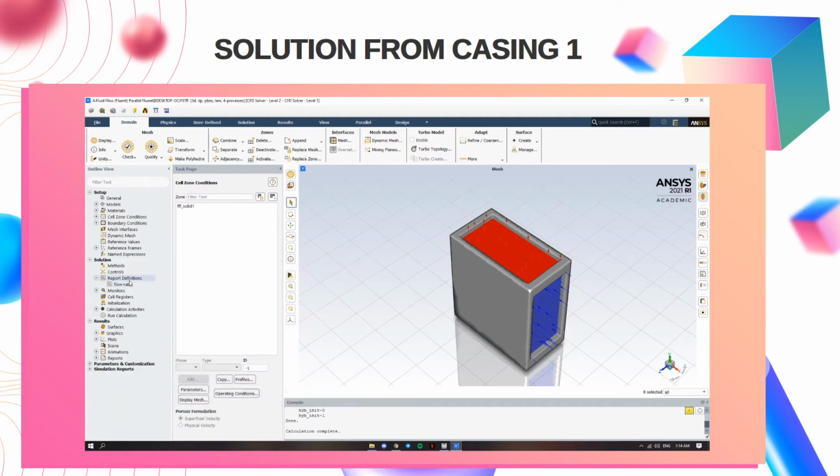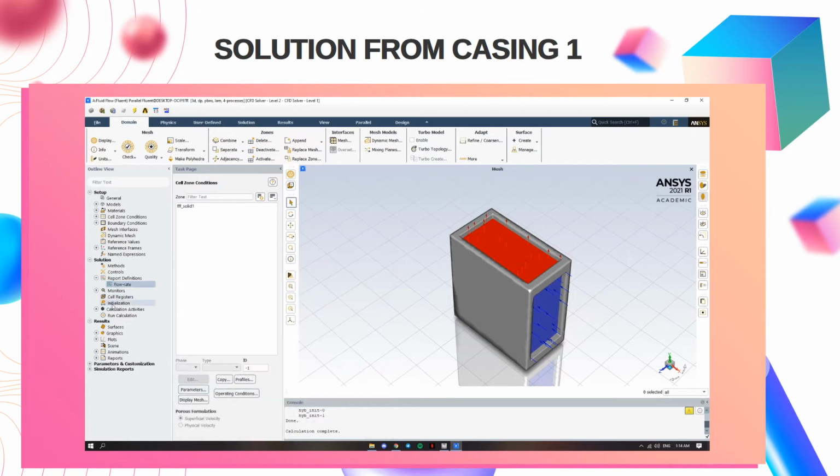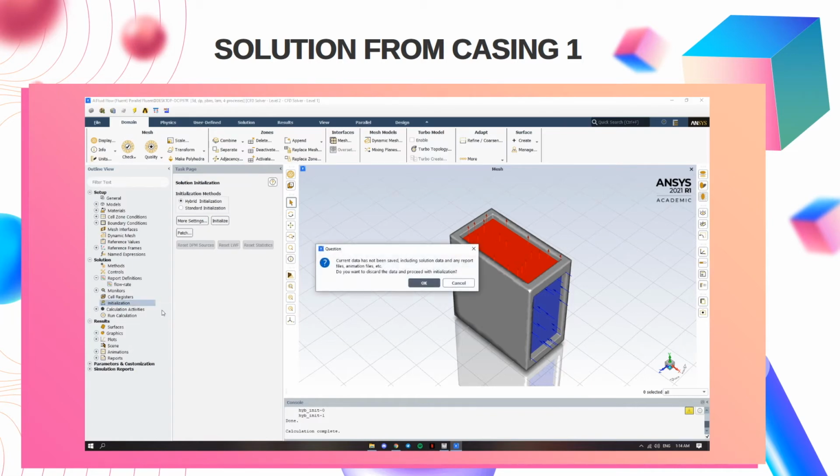Let's go to the report definition. For report definition, we select flow rate, or we declare flow rate as what we need from this analysis. From here, the field variable we use is velocity, and the surface, this is what you can see. All surfaces are needed for this analysis. Okay, next go to initialization. For initialization, just click initialize. So hybrid initialization is done.